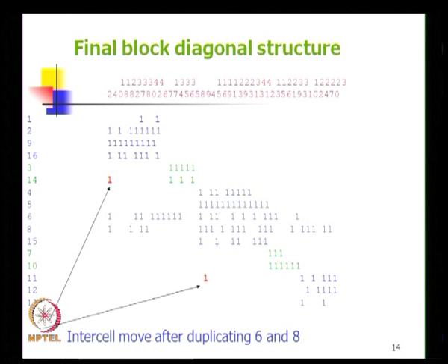So, the simplest thing first is to look at whether we can make some minor changes in the process plan, or look at existing machines in a cell which can carry out that operation. Second is to make some minor changes in the process plan so that it can be done in an existing machine. The third, of course, is machine duplication. Now, can I duplicate machine number 14 into the first cell also?